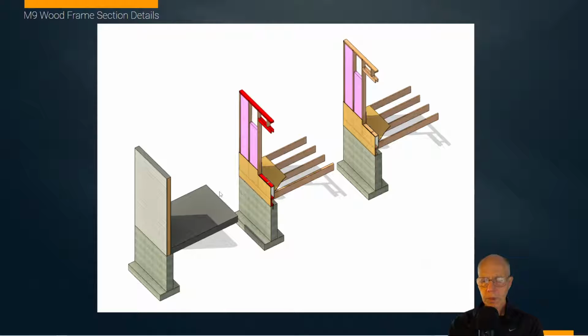We're going to bounce out to Revit here in just a minute. What I have here are 3 illustrations that I've created inside of Revit. The first one is how Revit would actually draw a wall system. Here we have drawn a wall that goes all the way down to the foundation. We placed a floor on the inside of the building. We have a foundation wall and a footer. But inside of this wall, we can only detail it as having a solid piece of wood, almost. We can't get to the idea of it having other kinds of structure. So in order to do that, we have to add those details in later.